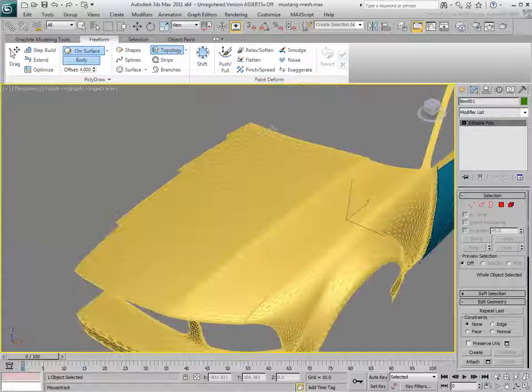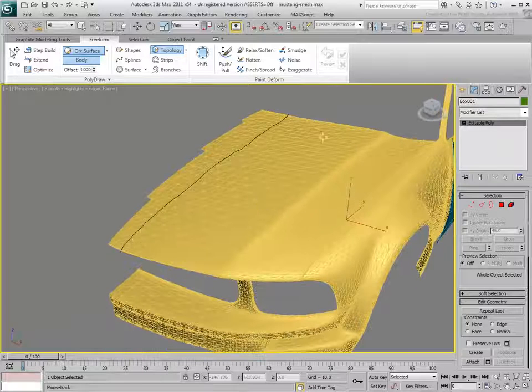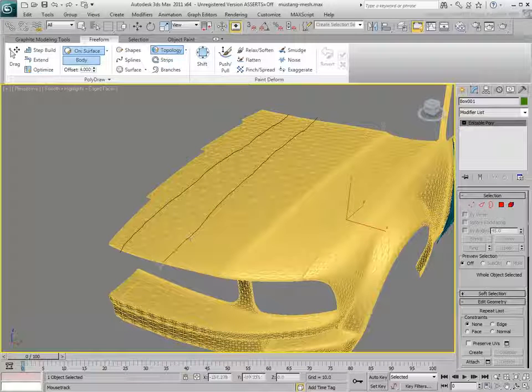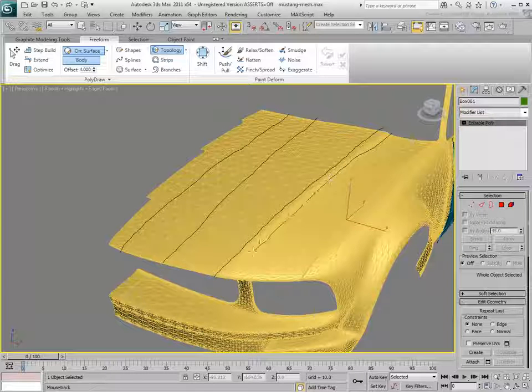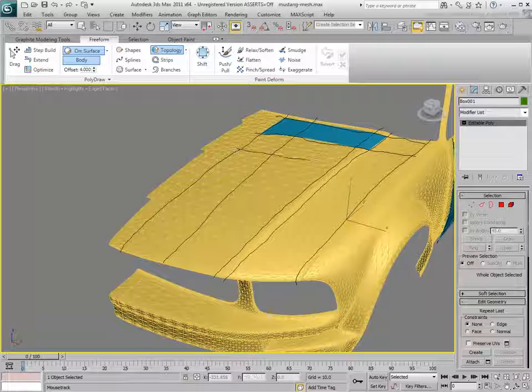Try the same technique to create the hood. Draw a few grid lines down the length of the hood, keeping some of the lines close where you need extra detail. You can then work on the crossing lines to create the surface. If your grid lines do not cross, you will get gaps in the surface. These are easy to fix, however.